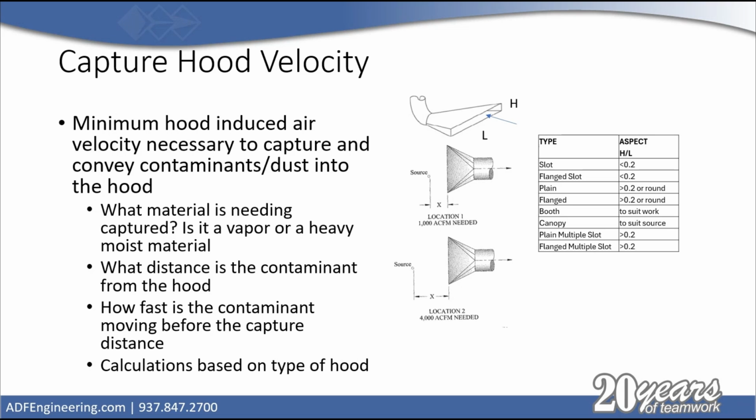So you need to take a look at what your dust is. So the big thing with aspirating dust is you need to understand what that dust is. What kind of settling velocity does it have? What kind of pickup velocity does it need to get it into the air? So that you can decide if you need to capture it or let it settle before you capture just the remnants of the less dense and less heavy portions of your dust. And the things to think of there are the distance from your contaminant